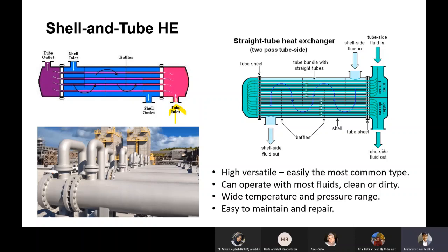So you get the liquid level equalized, and then it moves through the interior of the tubes to the outlet here. So that is one of the liquids, and another liquid is flowing through the shell side. For example, here in the illustration, it comes from the top left and goes through the shell. Inside the shell there is what is called a baffle.